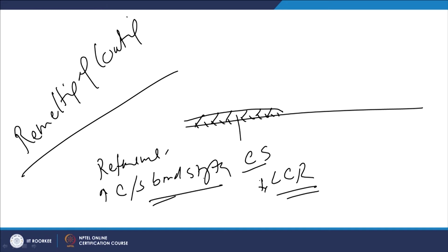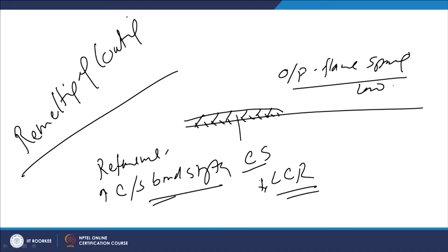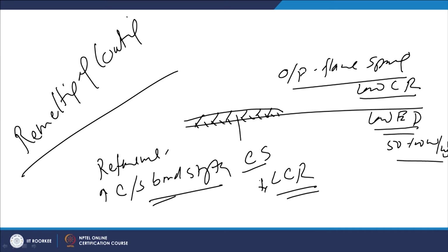In this particular approach of remelting the coating, since the oxy-fuel flame spray process offers a low cooling rate, because the process itself is of low energy density, very low, like 15 to 100 watt per mm square, a lot of heat is supplied, wherein there may not be melting of the substrate, but it gets a lot of heat and is preheated.